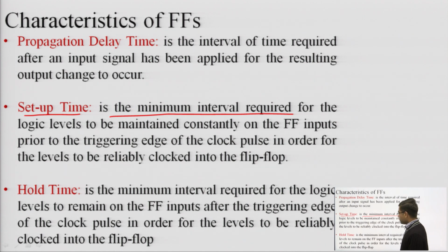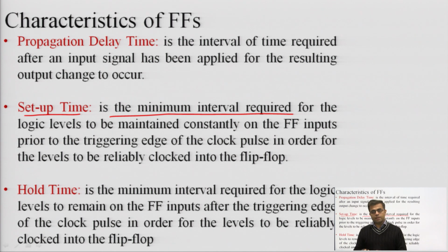Okay. Now, hold time. As the name suggests, the value which has been applied has to be maintained there. So, the hold time is the minimum interval required for the logic levels to remain on the flip flop input after the triggering edge of the clock pulse. The setup time is the minimum amount of time before the arrival of the clock edge. And this hold time is the amount of time for which the input must be maintained at that level after the edge has arrived.